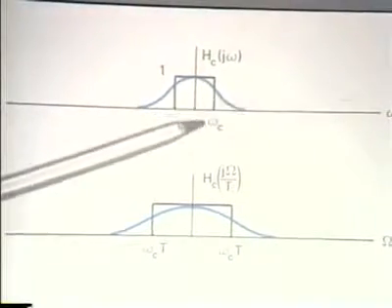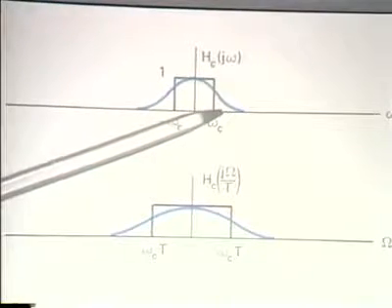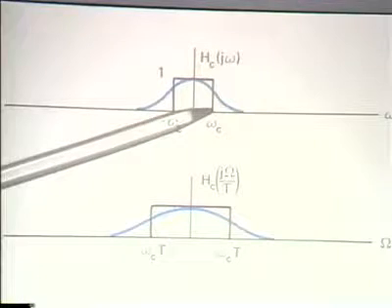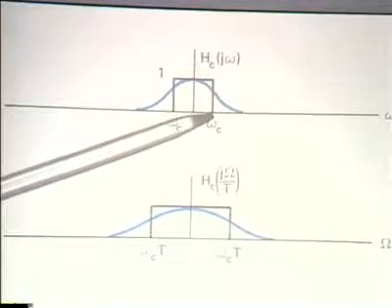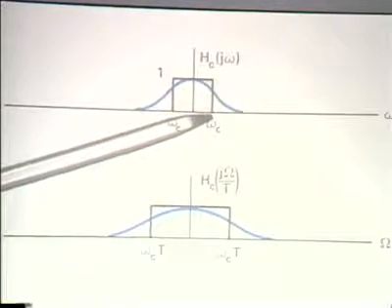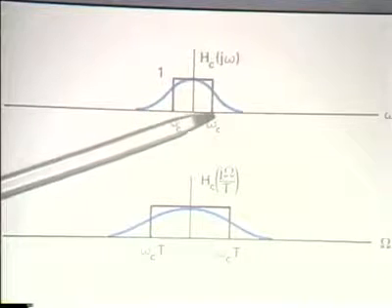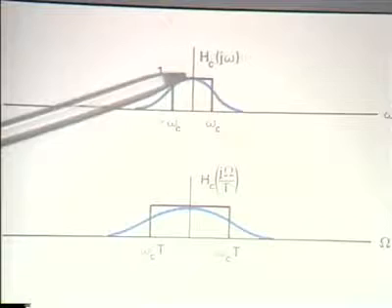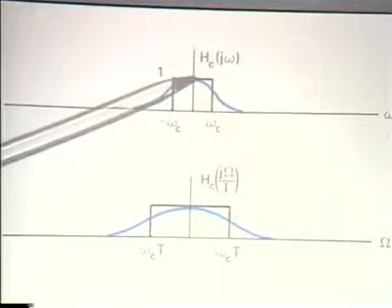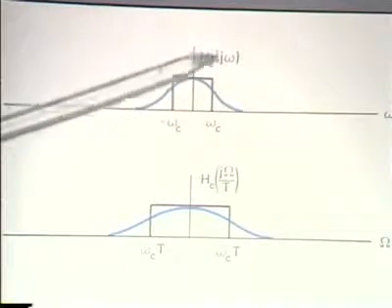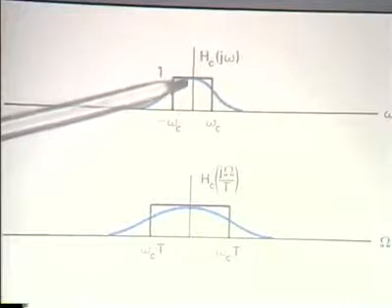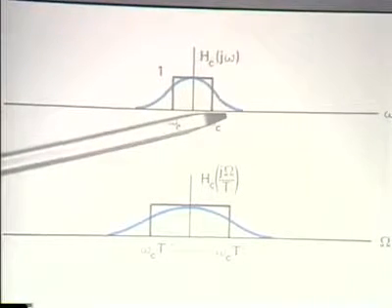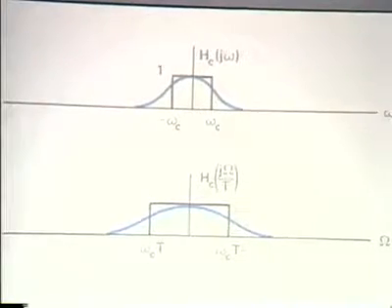And in particular, now, if we were to simply pick that parameter in the impulse invariant design, capital T, as equal to unity, and I indicated just a minute ago that we can pick it arbitrarily, then the procedure would consist of designing the continuous time Butterworth filter meeting or exceeding the appropriate specifications and then going through the impulse invariant procedure.